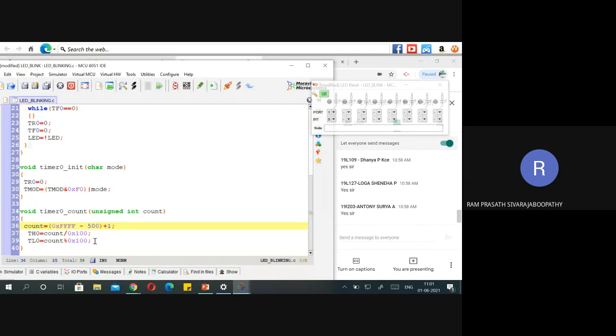Fine. So in this, what we are going to do is, so initially we are putting the count to be loaded. அதை நான் எங்க ஸ்டோர் பண்றேன் பாருங்க, நல்லா கவனிங்க. T0 underscore high. Instead of putting the value to the timer register, okay, counter register, I am saving it to the global variable T0 underscore high and low. High la வந்து higher byte இருக்கு, low la வந்து lower byte இருக்கு. Fine. So once it comes into this function, it will generate the count. So the count எப்பவுமே T0 high லையும் T0 low லையும் store ஆயிடும். That's it. Fine.